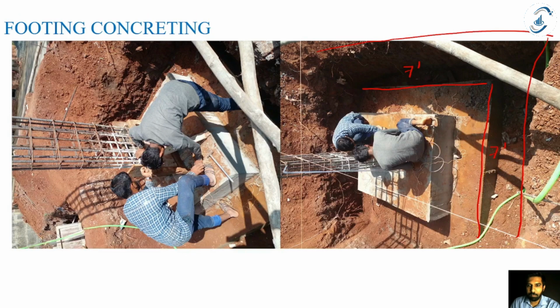Now we learned how to read my excavation pit size, how to locate them, how to read foundation drawings, that is how to read the length, the width, the depth of my foundation, along with the rebar details, that is what is the diameter of my rebar that is to be used along the length, along the width, and what is the spacing of the rebars along the length and along the width.